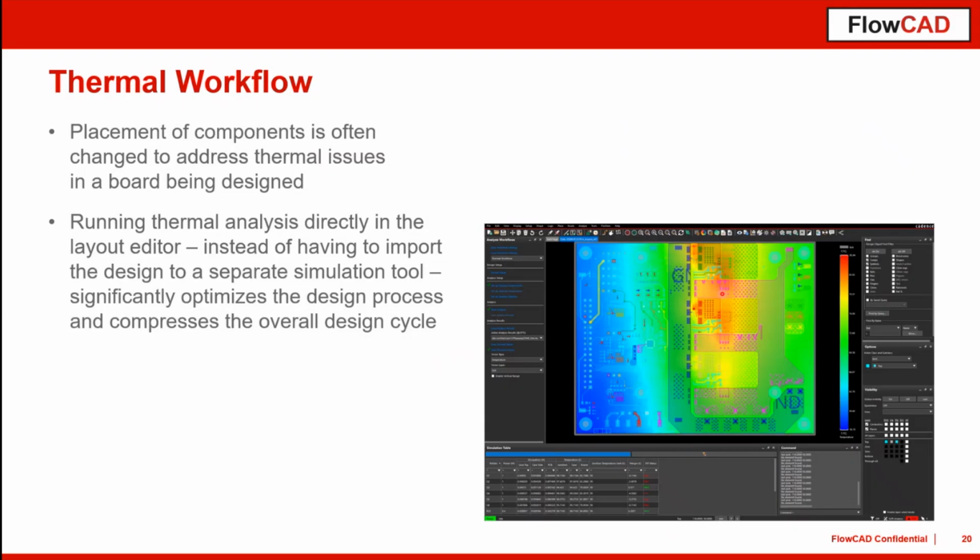It might be a very good way to check if it is possible to use half-ounce, 1-ounce or 2-ounce copper for your PDN layers, and to see if the temperature will be spread widely enough from the top to the bottom side and spread out across your design. And sometimes it makes sense to use thicker copper instead of using additional cooling equipment like heat sinks or whatever else on your components. So this can be done very early, as mentioned before, in the design process, and helps, for example, to save some money on additional cost of your design.